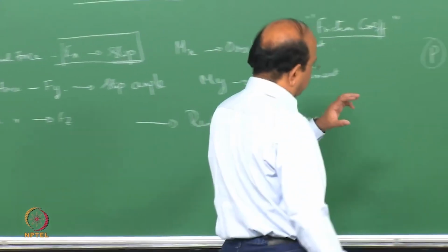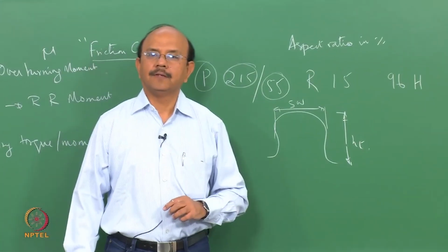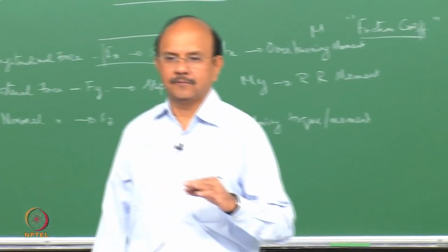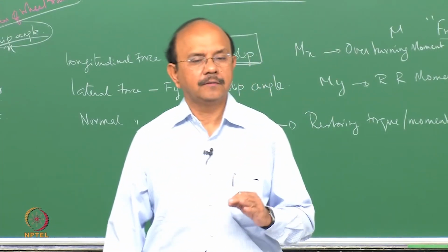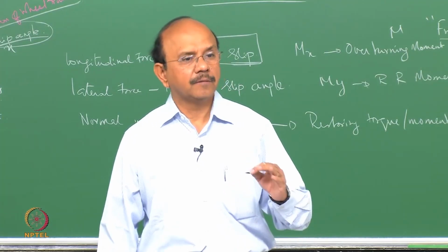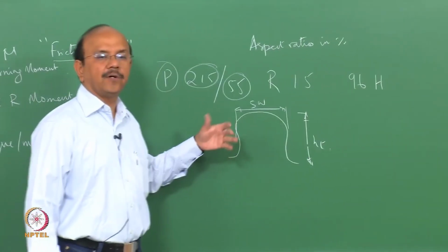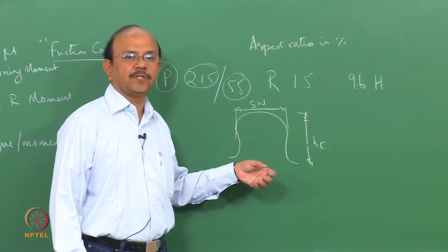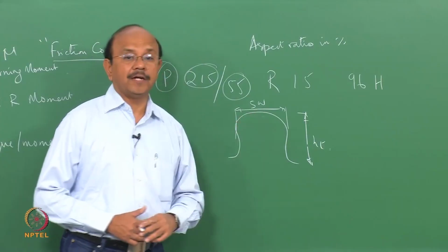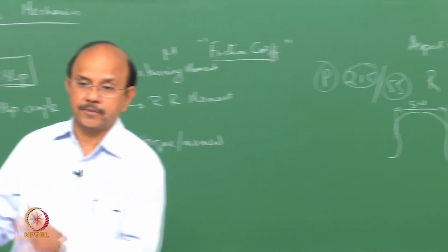These tires have a specific characteristic: they make handling much safer. On the other hand, the ride becomes quite wobbly, in other words, it has a negative effect on ride and a positive effect on handling. So the low aspect ratio tires are usually compensated by a good suspension system.